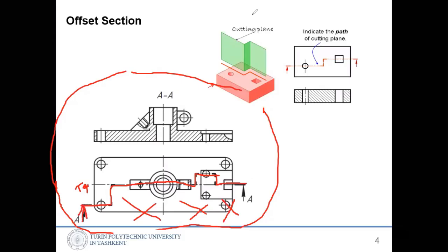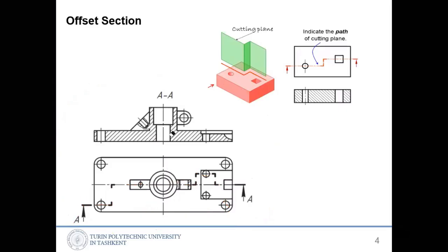And what we see is the solid thing, and this is front view, but front view is replaced with section view. If you have a front view and section view outside, you can replace the front view, and instead of front view you can show the section view AA. So we're cutting with AA plane, and that is AA shown here.